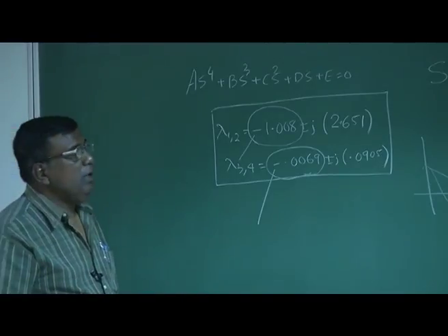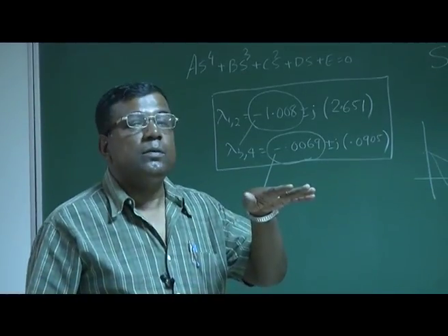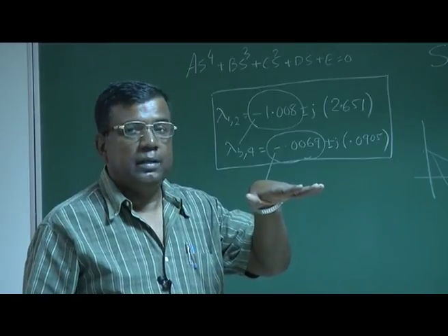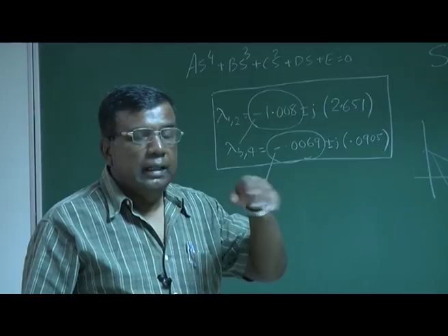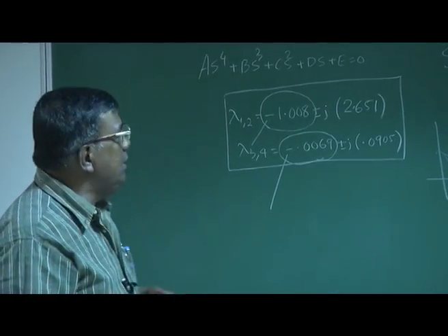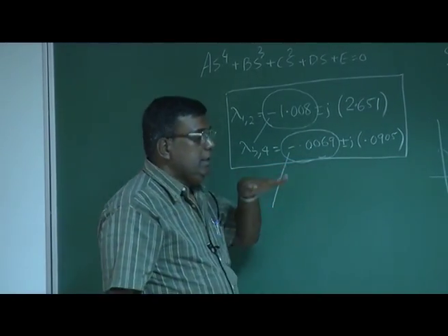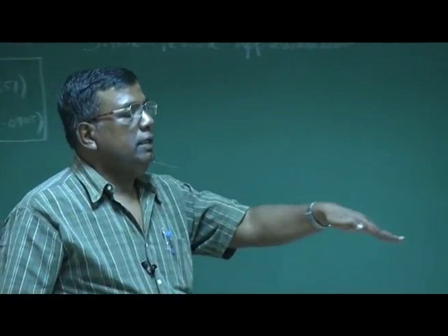And physically what we understand is, when an aircraft is disturbed, it has primarily two modes of excitation. One is short period, where you disturb it and it immediately comes back. During this short period mode, you can understand there is not much change in the velocity u. However, the other is a long period because it takes longer time, and it is called the Phugoid mode. It oscillates like this and then comes to equilibrium.